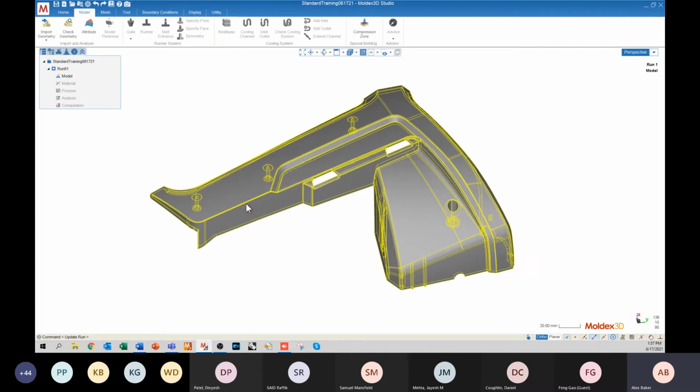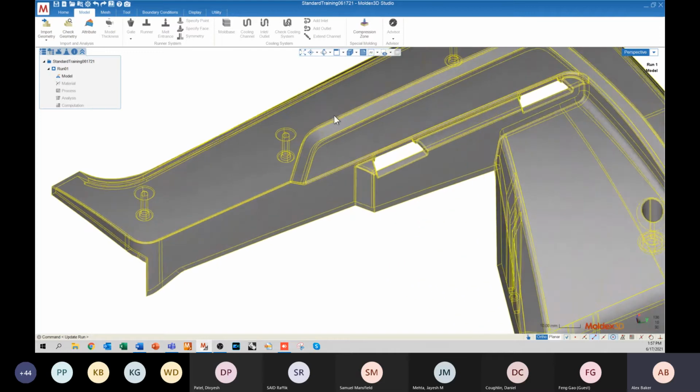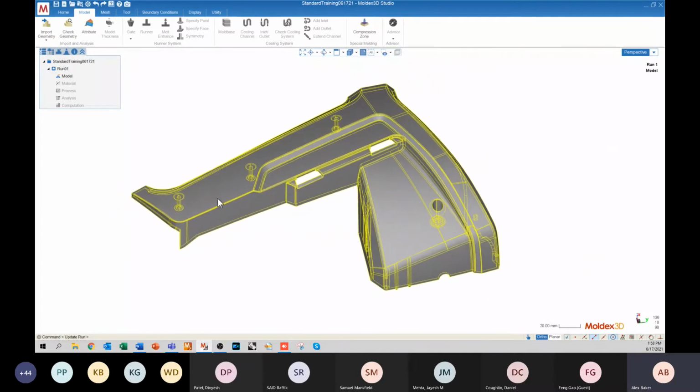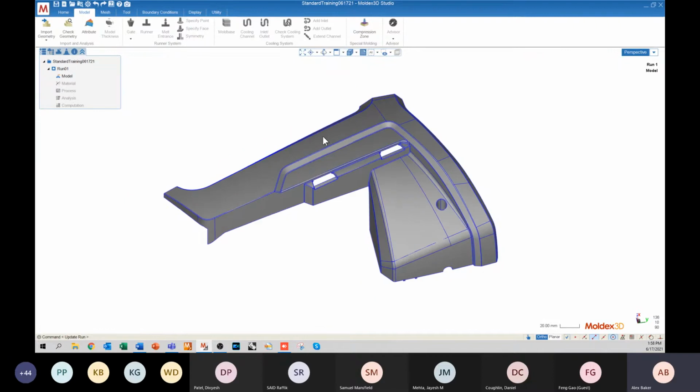All right, that turns all of the feature lines on your part from blue to yellow, and it's just kind of an obvious indication that you have selected your model. But there are a couple of other options that you have for selecting as well in the form of what we call box selects. So box selects are going to be enabled through a left click drag.